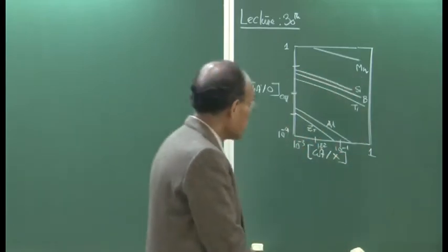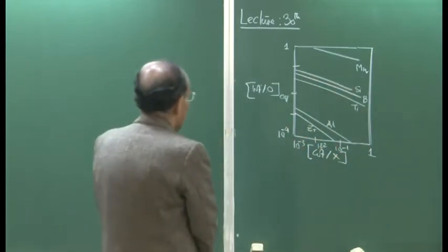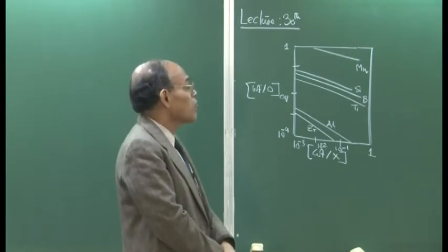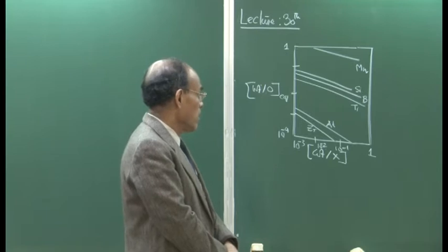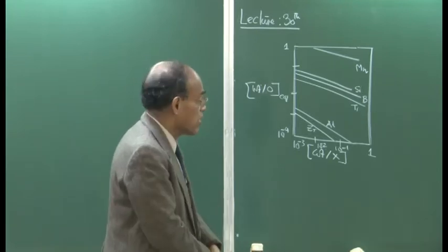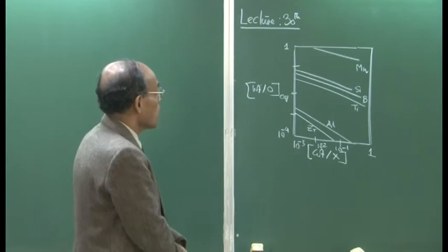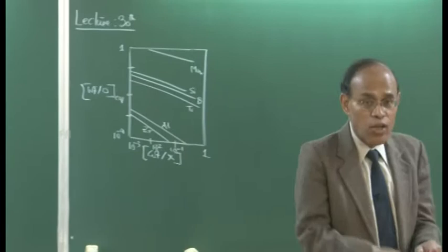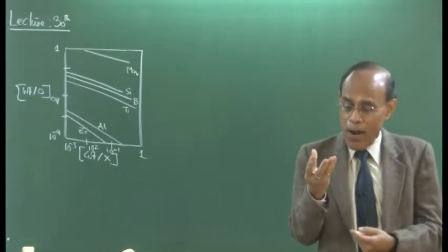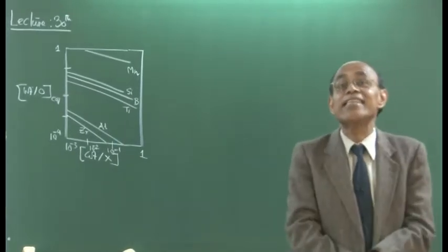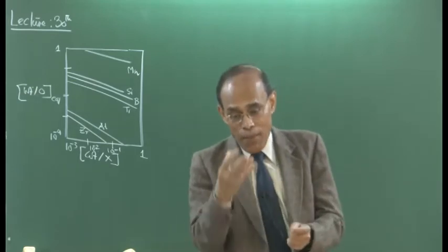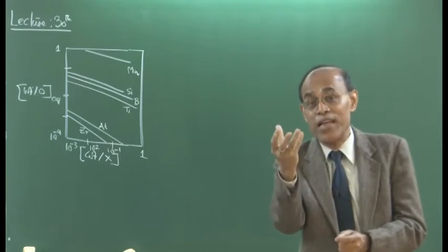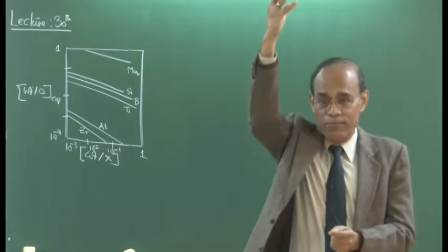So, I would also like to demonstrate, before I end the lecture on deoxidation, a sample calculation, and to illustrate this aspect of deoxidation calculation, I just want to emphasize that yesterday, in the last lecture, I mentioned that a part of the deoxidizer goes inside the metal, stays in the dissolved form, and a part of the deoxidizer reacts with oxygen, and that is an oxide product, that is the deoxidation product, and that floats up.